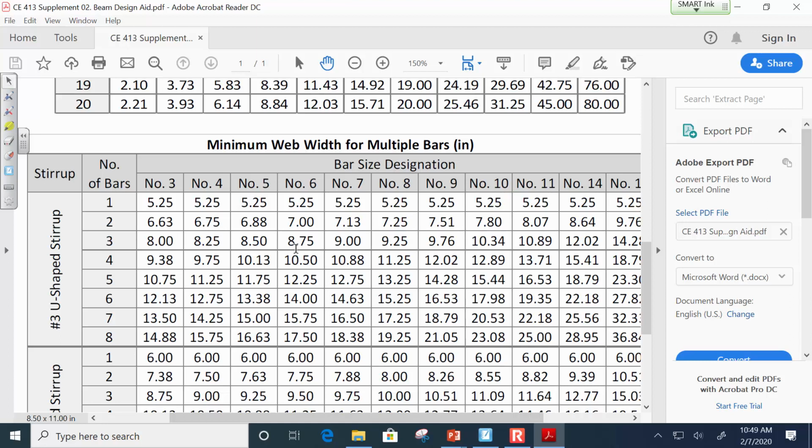So what we'll do is pick a family of reinforcement patterns up top, and then check to see, okay, for our problem, are these patterns even going to work? Are they going to fit inside the beam that we design? And if not, we'll move on to the next one. We'll have a beam design problem, we'll probably pick like 4 or 5 different reinforcement patterns. 2 of them might not work because they're not going to fit, and of all of the remaining reinforcement patterns, we pick the one that has the least amount of steel. And that is how we go about design.